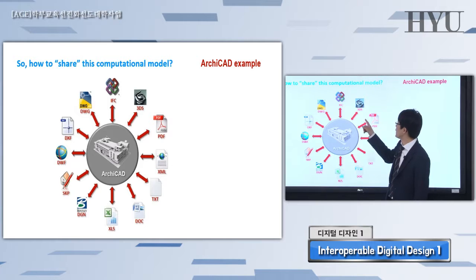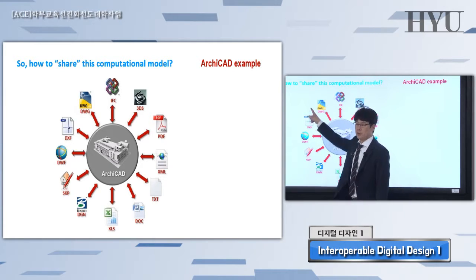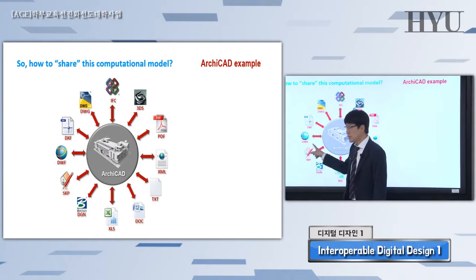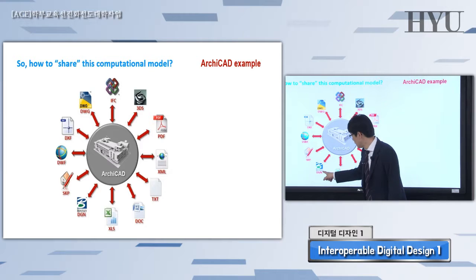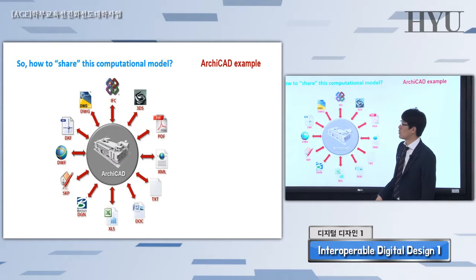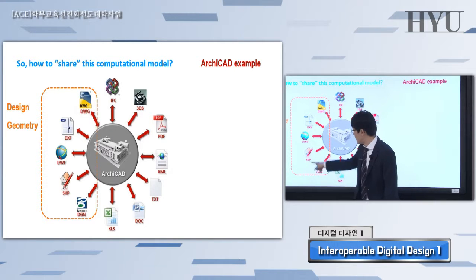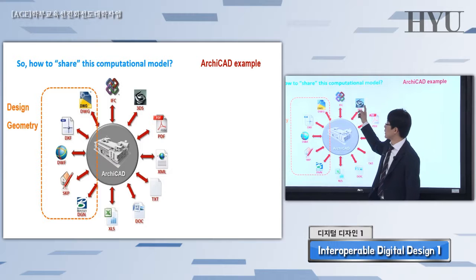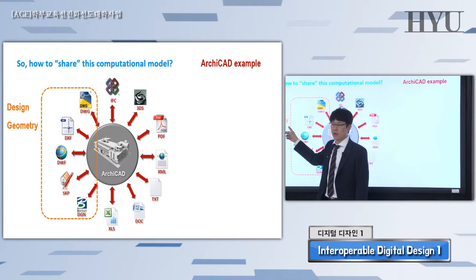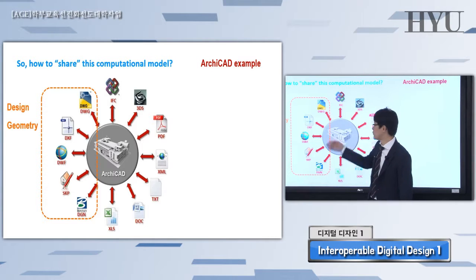You know that, right? 3ds file, 3D Max file, DWG, you know this, legacy CAD file, usually 2D or 3D, DXF, DWF, and SketchUp file, okay? Your favorite SketchUp file, Bentley system file, and so on, okay? Actually, these files and the 3ds file, they are design geometry files, okay? Mostly they contain geometry in 2D or 3D, usually 3D nowadays.